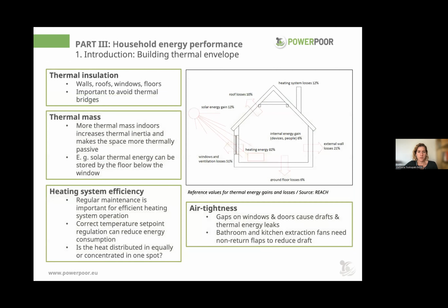Regarding the building thermal envelope, some things that we need to have in mind when visiting a household: we have to have a general overview of the building envelope. It is very important to understand if there is thermal insulation in the envelope, if walls, roofs, windows, or floors are insulated. And it's very important to avoid thermal breaches, which we will see later.